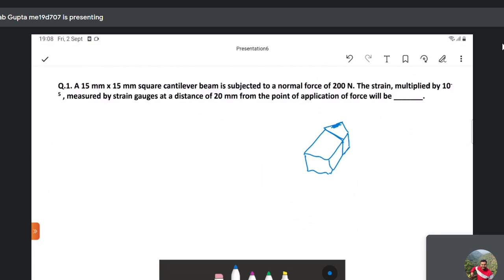Then this will be your rake surface, and this particular surface that's facing away is the flank surface, and it is interfacing the workpiece somewhat like this. It is being imparted a rotational motion, and the tool is imparted a feed motion.